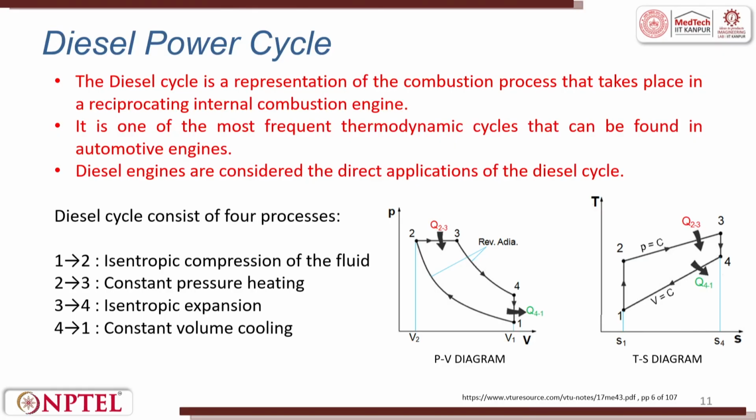To recall, the concept of the diesel power cycle is just like the Otto cycle, another representation of the combustion process that takes place in a reciprocating internal combustion engine. The Otto power cycle was a typical spark ignition piston engine. The diesel cycle is for a reciprocating internal combustion engine, one of the most frequent thermodynamic cycles found in automotive engines. Diesel engines are considered the direct applications of the diesel cycle.